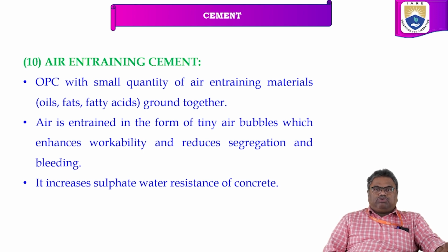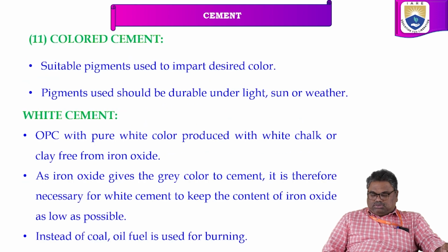We will discuss this in concrete properties: what is workability, what is segregation, what is bleeding. We'll discuss at that point of time. As of now, this air entrained cement enhances the workability and reduces segregation and bleeding. It also increases the sulfate water resistance of the concrete. This is air entrained cement.